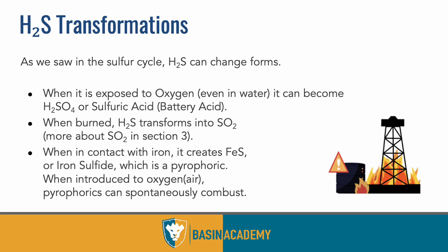And that itself can auto combust, auto ignite when it's exposed to O2. So, when it's in old flow lines or abandoned pipelines, we're digging those things up. If we don't wet that pipe or fill it with water and cap it, preventing oxygen from entering it, it can catch fire. So that's something else to note about H₂S. Yeah, it's an intense gas. H₂S is quite an impressive chemical, just by and large. I don't want to call it the ninja gas, but it is kind of the ninja gas. Finds every little nook and cranny, and has 100 different ways to kill you.